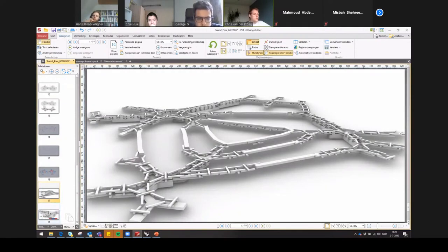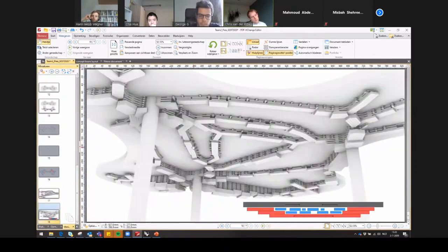And then the next step, what we were thinking, is to connect it to a timber floor. So the floor itself can also provide one of the flanges of a kind of beam. Which made us move further towards a sandwich structure, where the bottom of the beam is again solid, and the top of the beam is also solid because it is the slab itself. And the intermediate structure can be way more fine or separate elements, for which we use the original script,